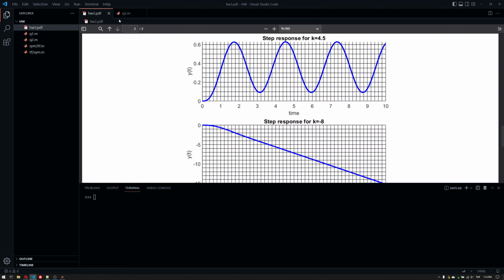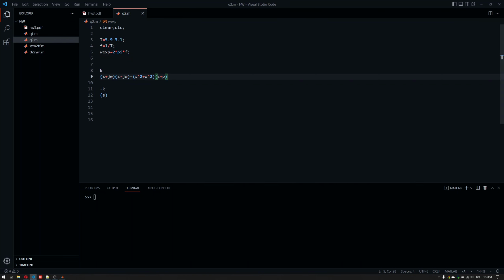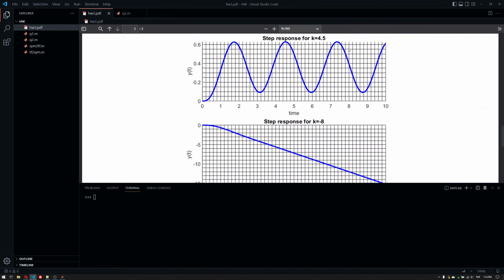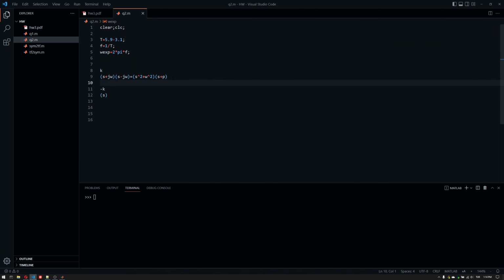And the reason for that is that the inverse Laplace of this whole thing, omega squared p divided by this whole thing in the denominator, would give us some sinusoidal terms and some exponential terms, but the sinusoidal term will be important because it is a constant sinusoidal wave here. So basically, this corresponds to a j omega crossing, and therefore we get a sinusoidal output.